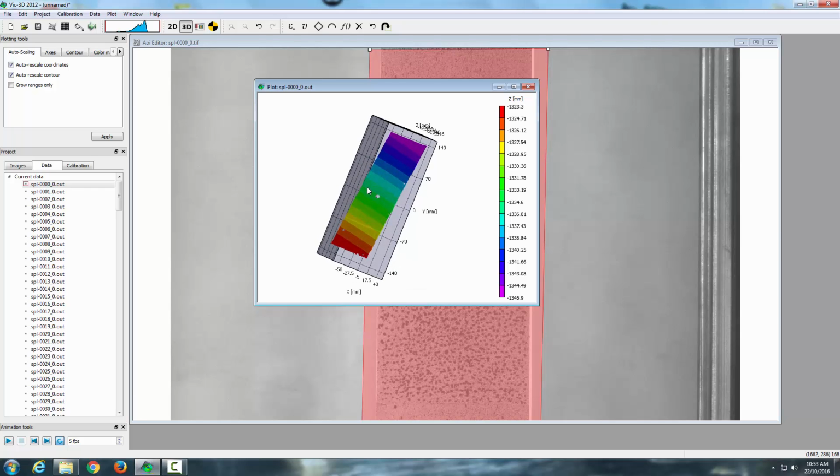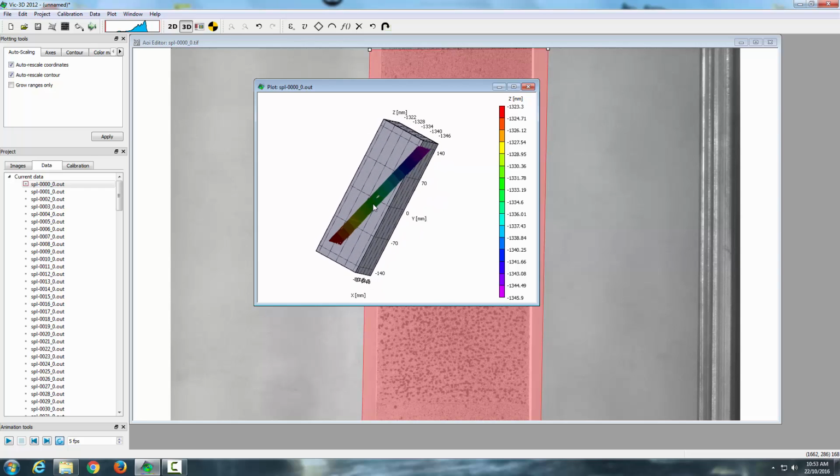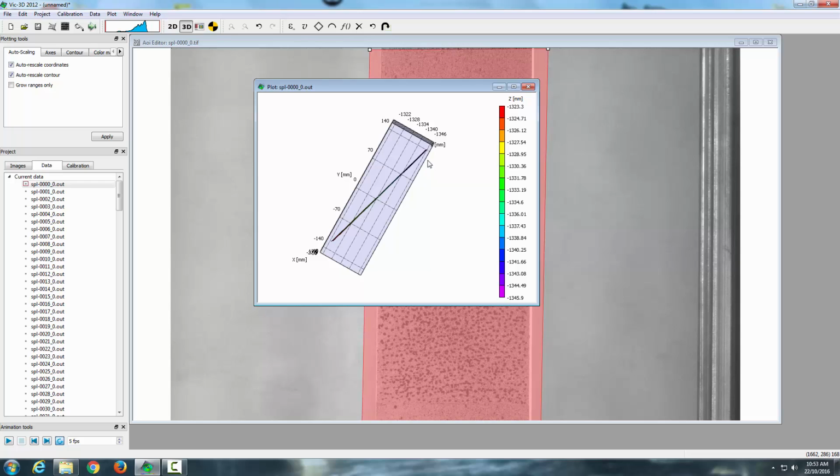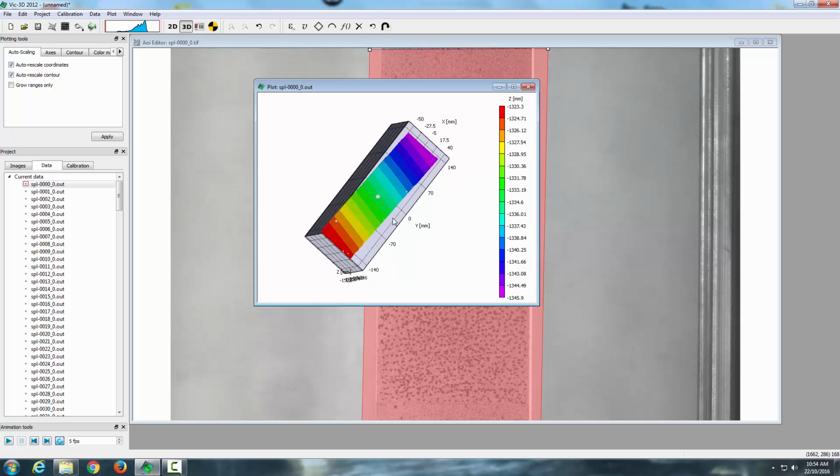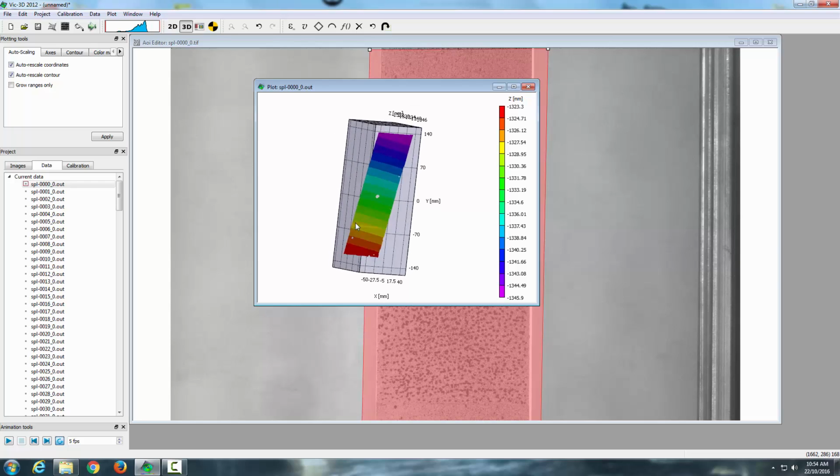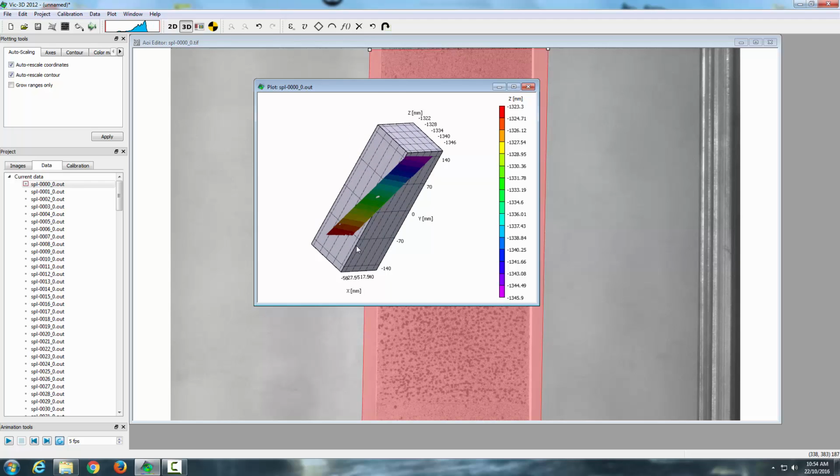Okay then, so we've processed our data, everything looks pretty nice and spiffy, a couple of little holes here and there, but there's nothing to worry about. But why is it all angled so funny relative to our coordinate system? What's going on there? Now it's actually done that because I didn't check a box before, which would have done an auto plane fit based on this plane, but I've done that for a reason. It's just purely to explain a little bit more behind what the software does.